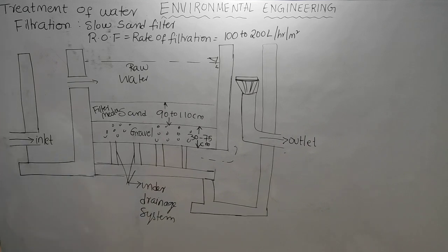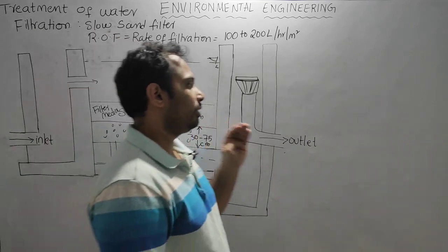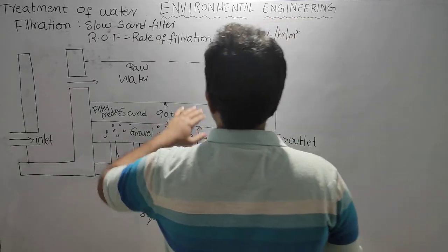If you don't remove it, it makes the filter unfit for any kind of filter operation. It will not allow any filter operation. Generally the head loss of the filter varies from 5 centimeter when it is clean to 90 centimeter when it is completely full of impurity.